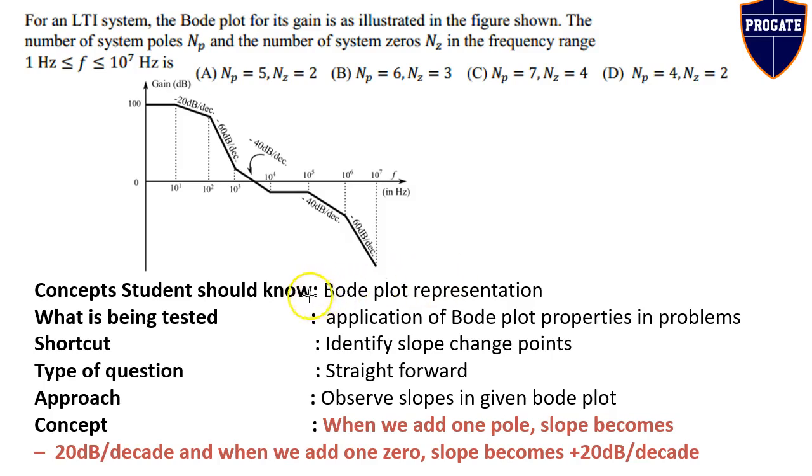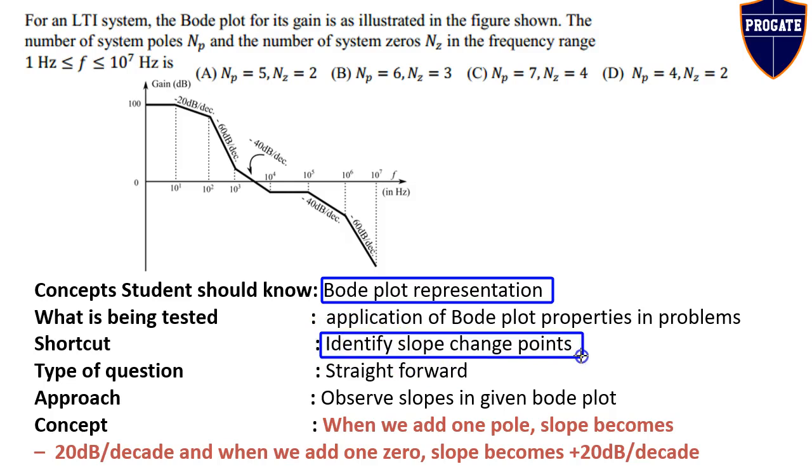The concept the student should know is Bode plot representation. Application of Bode plot properties in problems is being tested. The shortcut to solve this question is to identify the slope change points. So in this given figure, the slope change points are these points.